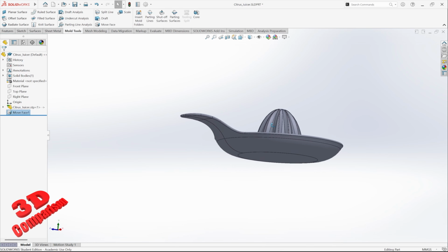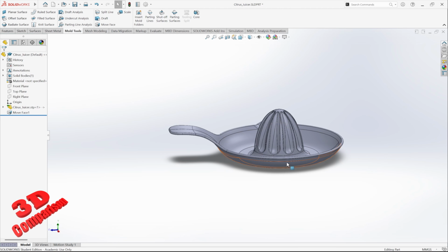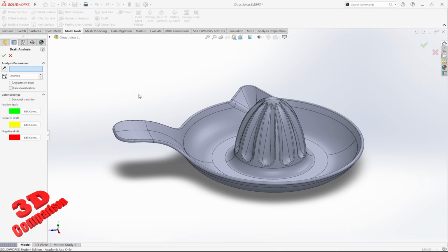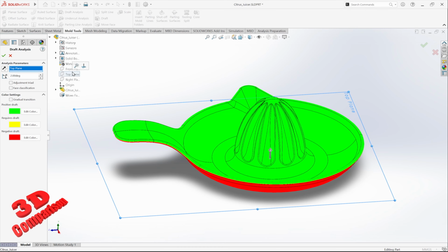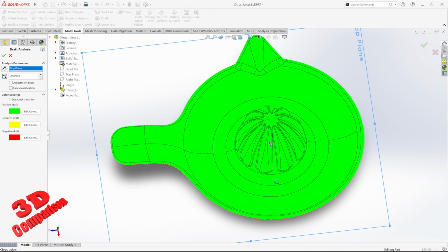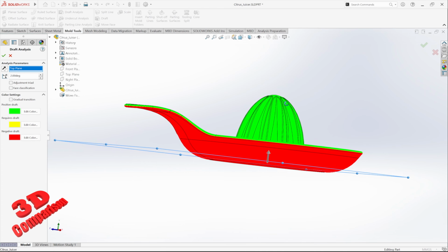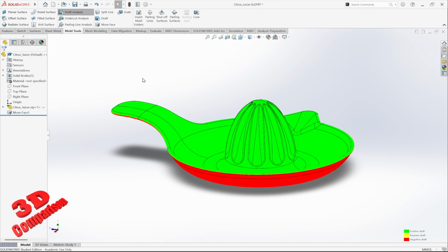So now also you're going to see that the default shadow within SolidWorks will be casted like this. So we want those two tooling splits, one to go upward, one on the bottom. So we can go ahead and we can design a draft analysis. Now, when you are designing and applying this draft analysis, you can also use the predefined planes in this case. And we're going to see that for 2 degrees, in this case, this will be how those tooling splits will be. So this will be more than fine.